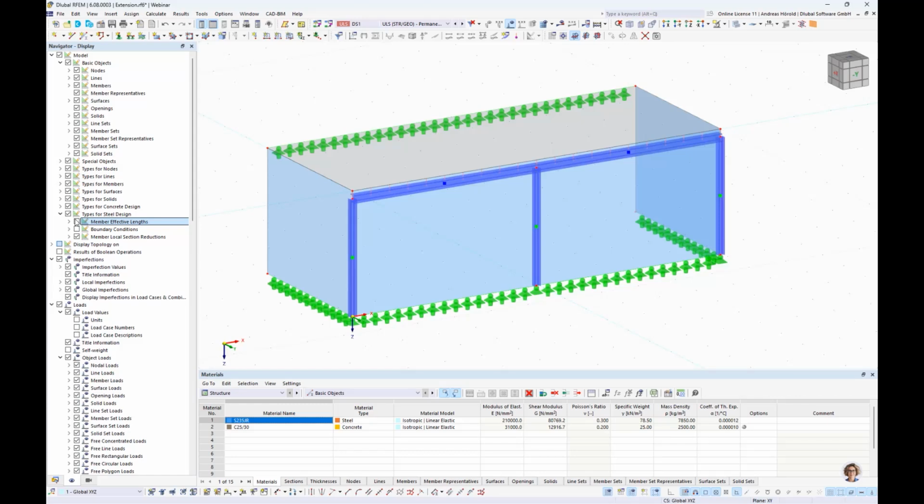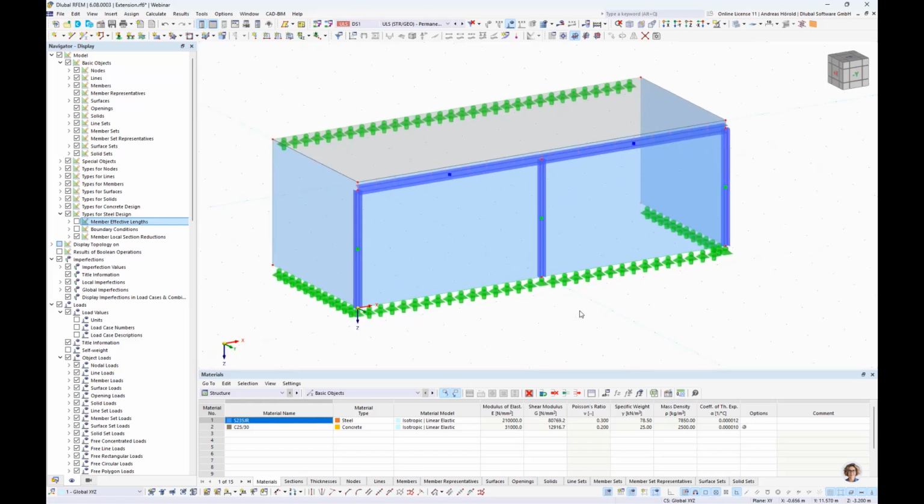So, okay, we don't define any settings for the horizontal beam. We don't want to do a stability design. We imagine the HEB 200 is supported enough by the concrete slab. And that's why we don't create any settings. And then only a cross-section design will be done by the program. And you can see it's no longer necessary to create cases as in RFEM 5. It's much more flexible in RFEM 6. Let's run the calculation or the steel design.